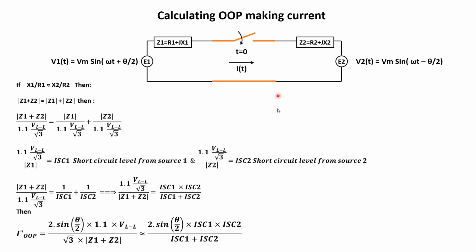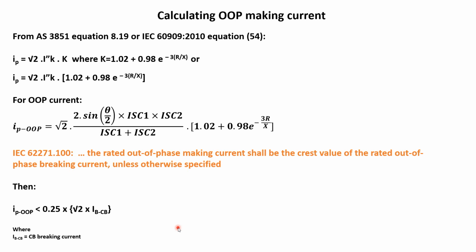You see if there is a zero angle, it is going to be zero current. If it is a very low angle between them, there should be very small current. So it doesn't matter that I use the word short circuit, it really depends on the delta difference between the two sides.